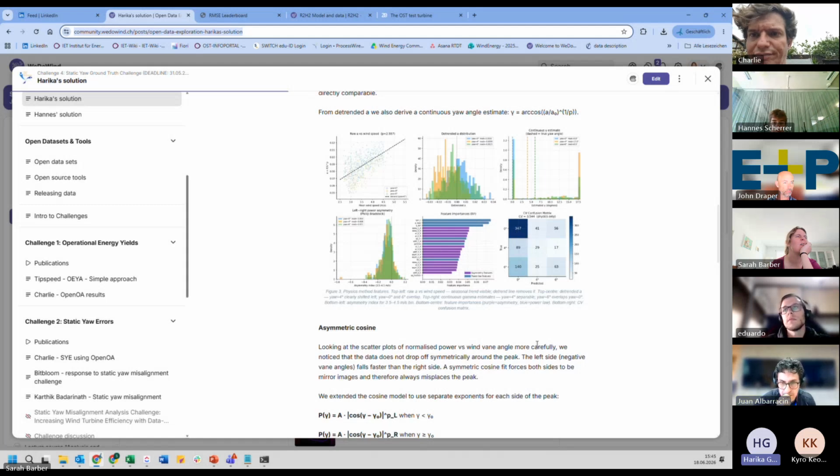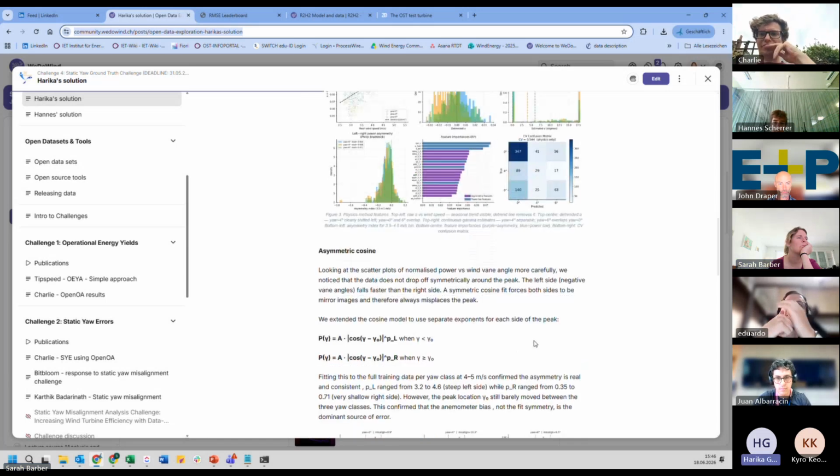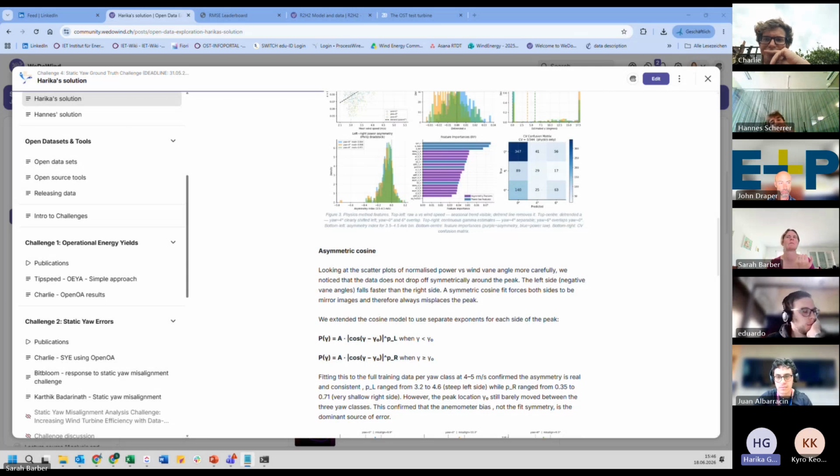Yeah, and even with the earlier power curves, what I could see is you could still detect a 4-degree, but then the 0-degree and 6-degree had very little power. They were in such an overlap that it was getting really difficult to differentiate between both the values, or both the data points. So that is something I'm not 100% sure of, but I was able to differentiate the 4 degrees yaw.